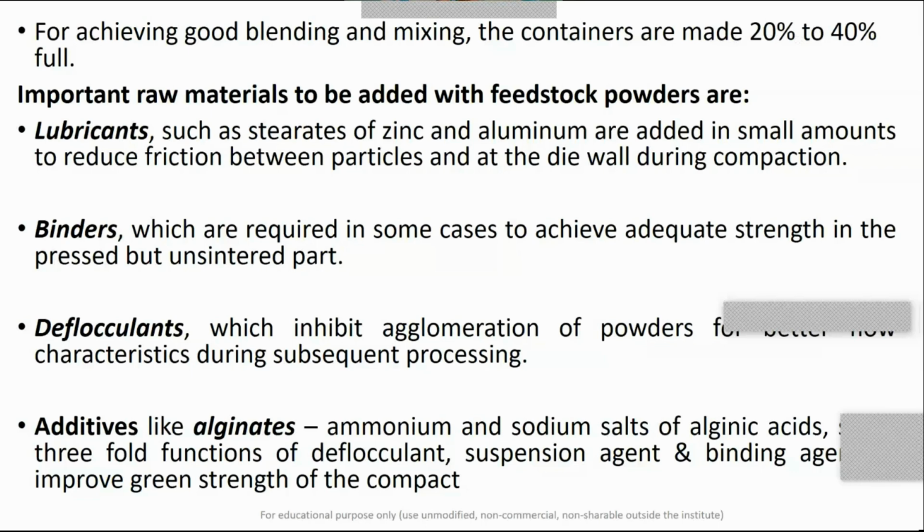And we have some binders. Binders are required in some cases, not always, to achieve adequate strength in the pressed part before sintering. Whatever binder you add into the powders will be burned off. It will be liberated in the sintering step.